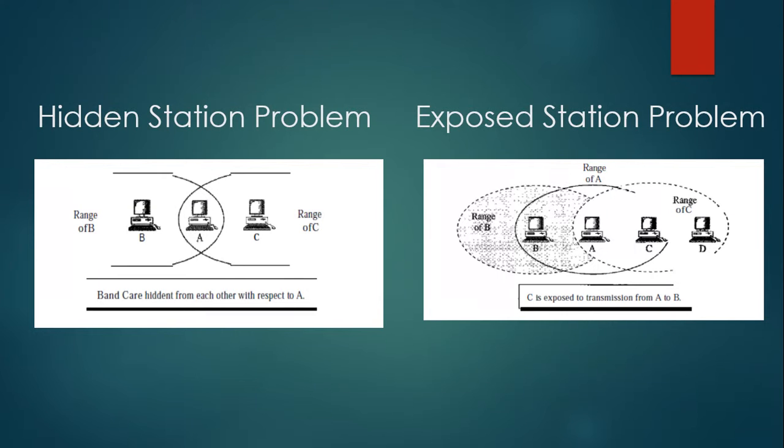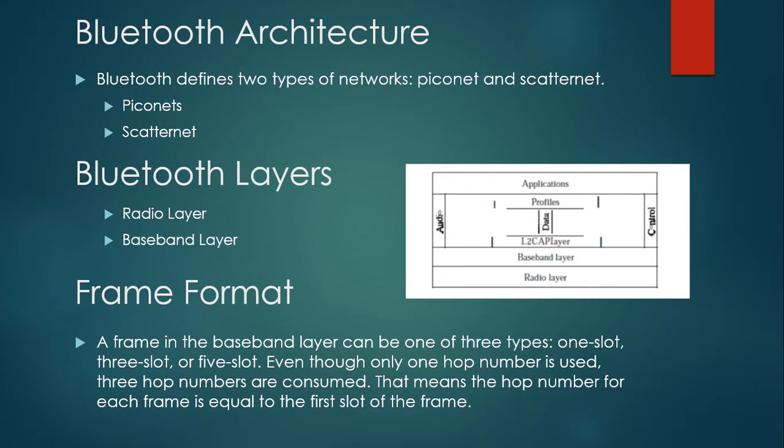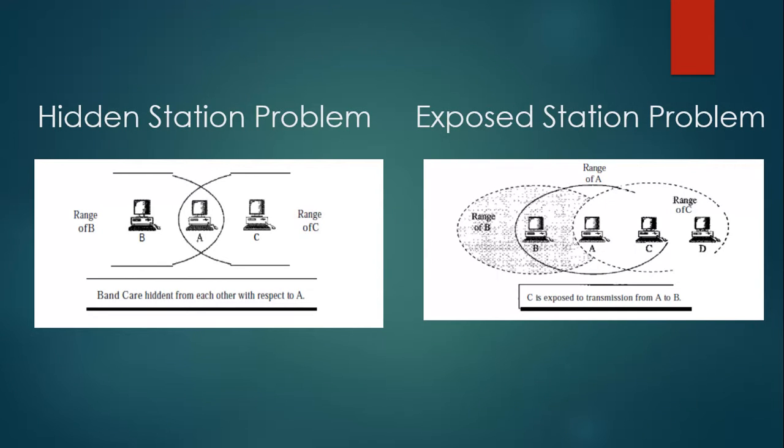Now we'll explain the IEEE 802.11 physical layer feature. The initial 802.11 standard defines two forms of spread spectrum modulation for the physical layer: frequency hopping and direct sequence. These two standards specify a 2.4 GHz operating frequency with data rates of 1 and 2 Mbps. Another initial physical layer utilizes infrared passive reflection techniques and transmission of data at 1 and 2 Mbps. However, this standard has not been implemented in products.